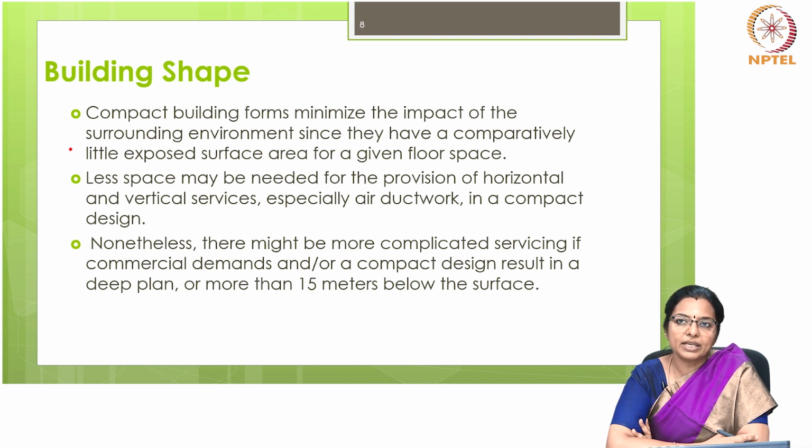Less space may be needed for the provision of horizontal and vertical services, especially air ductwork, in a compact design. Nevertheless, there might be more complicated servicing if commercial demands or a compact design result in a deep plan of more than 15 meters.